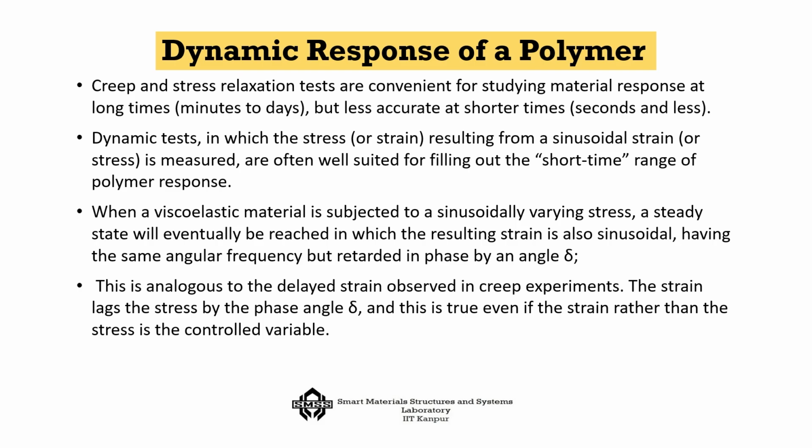Now, creep and stress relaxation tests are very convenient for studying the material response at long times, but they are less accurate at shorter times. Dynamic test, in which stress is resulting from a sinusoidal strain, is a short time response. So, viscoelastic polymer long time response is important, as well as the short time response is important.